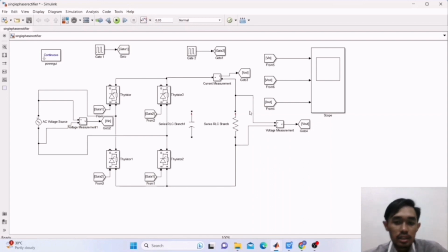So the switching of the current direction results in a unidirectional current flow, which is the basic principle of rectification. The design of the bridge rectifier should take into account the voltage and the current rating of the diodes used, as well as the load impedance. The diode should have a sufficiently high voltage rating to withstand the maximum input voltage, and a current rating to handle the maximum current flow.